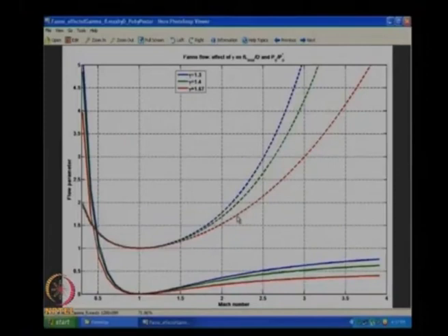If I think about the compressible case, for the same Mach number, P naught drop is a lot higher in supersonic condition compared to the less compressible case. If it is more compressible, the energy drop, P naught, is much higher. And in subsonic, there does not seem to be any difference, they are almost on top of each other. Just remember that if there is compressibility, there is going to be more P naught variation. Same things we saw in shock also, we will not discuss that right now. I told you that is out of scope for this course, you will just ignore it that way.